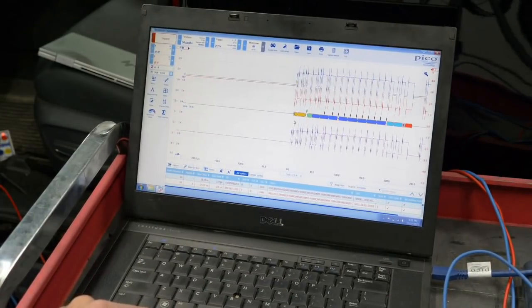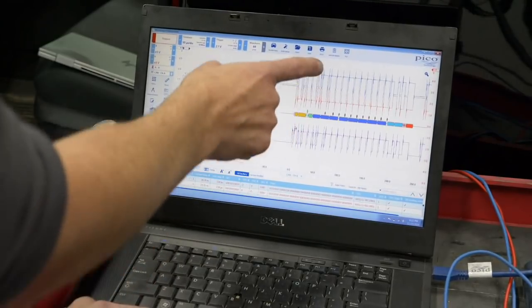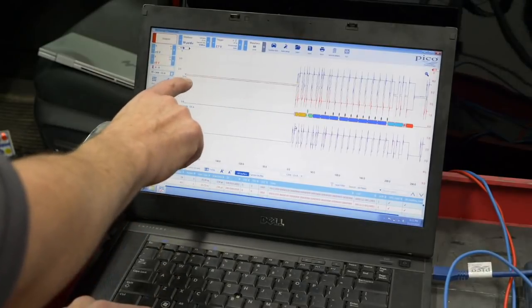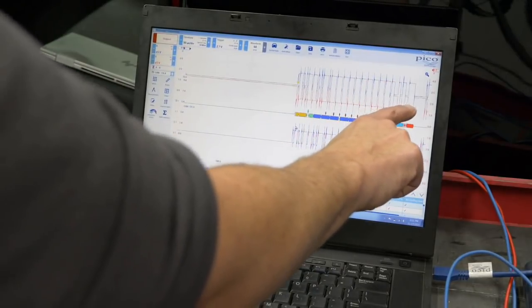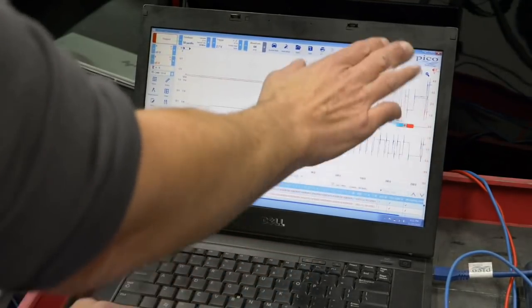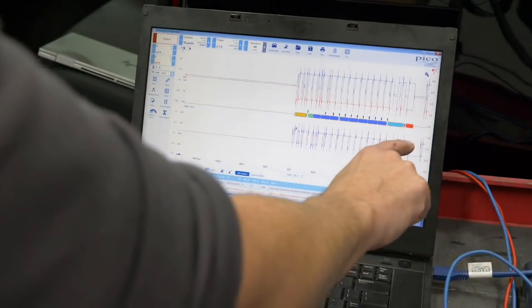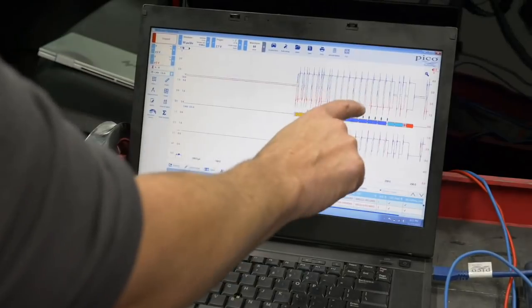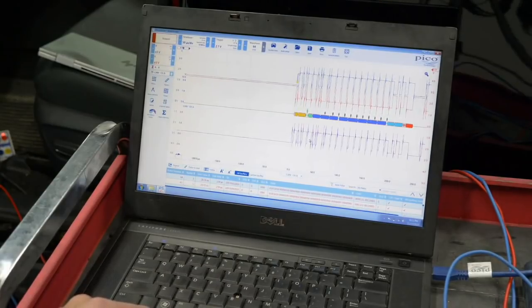Yeah. And some of you guys are probably wondering, well, wait a minute, how can I get that from here? Because these are opposing, so if you're subtracting B from A, you should get 0. Well, remember our amplitude. We're up at about 2.9 volts, almost 3 volts up here, and then down here we're at about 1.5. So when you're subtracting them, you're getting a little over 2 volts, and that's why we see the difference here. So it's not like this center line is 0. Just in case you were wondering that, guys, because it looks like you subtract B from A, you get 0. But Chad, this would be the actual data signal that the modules use, right?